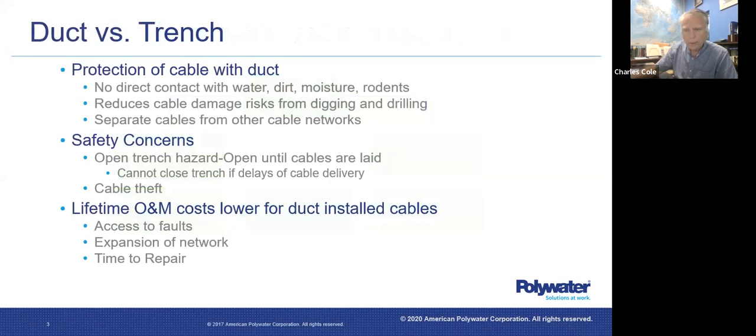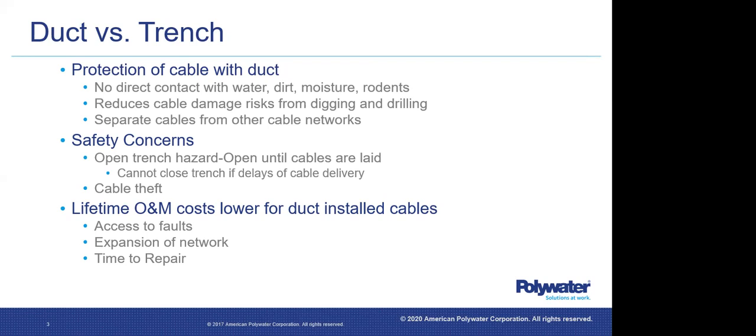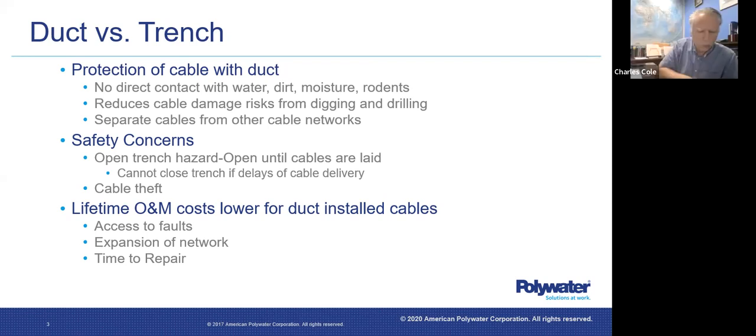Let's take a look at reasons why people install in duct versus an open direct buried trench, or the cable being installed in contact with dirt, mud, water through a reverse bore HDD technique. First of all, when cable is installed in duct, there's a lot of protection of the cable inside the duct. There's no direct contact with water or dirt, and it reduces cable damage risk from digging and drilling, which happens a lot, especially in urban areas.